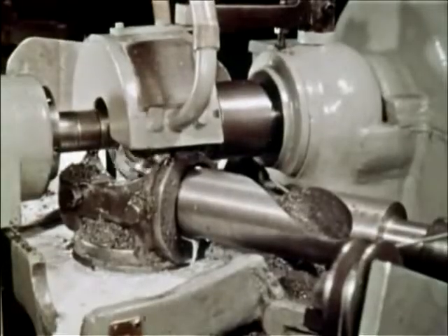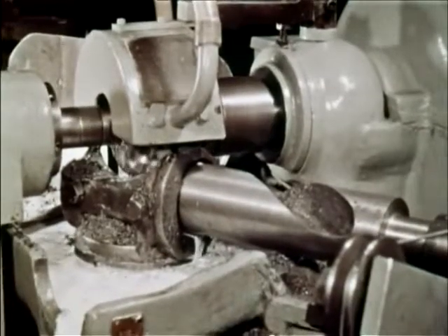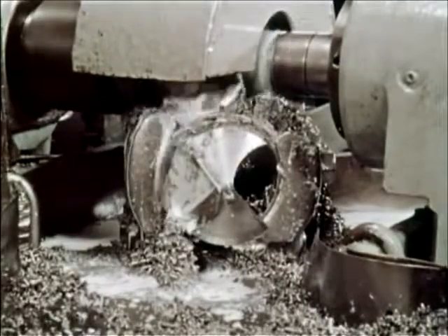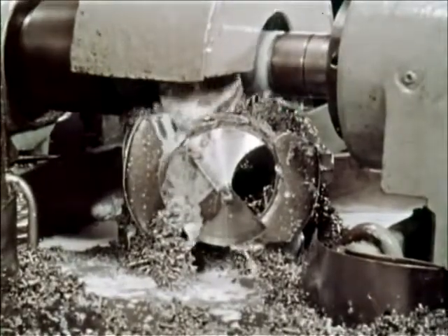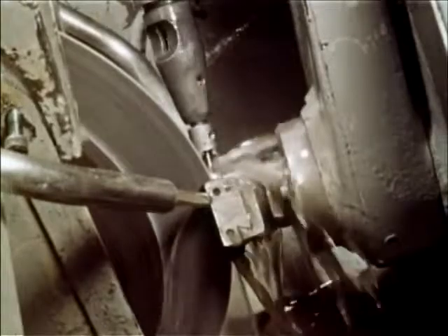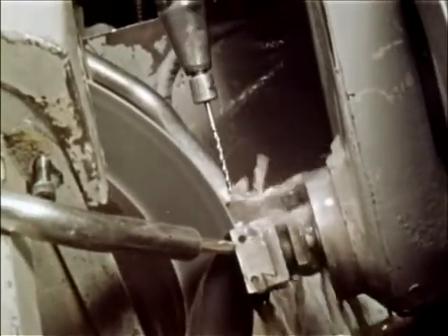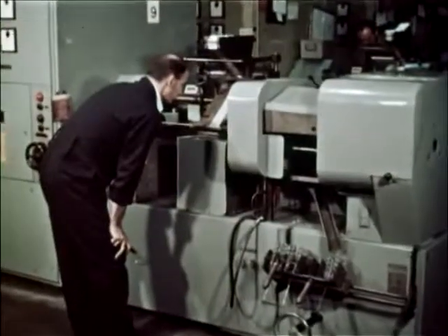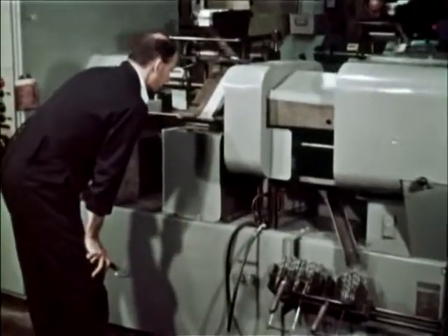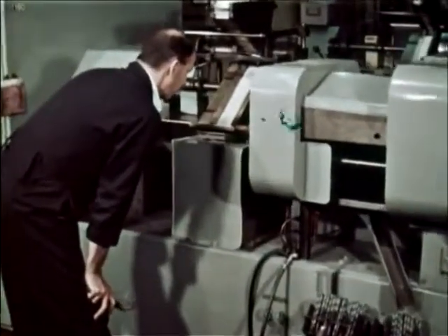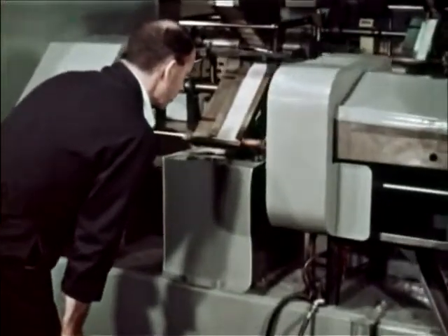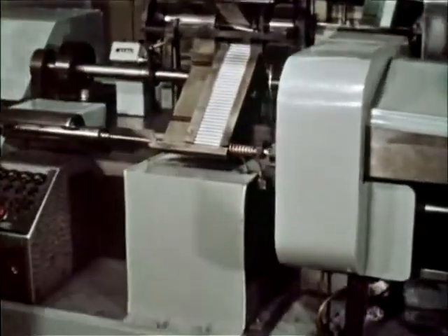The flutes of the drill are specially shaped so that when the correct point angle is produced, the cutting lip forms a straight line. The flutes of smaller drills are produced by grinding. Another method is roll forging, where the high-speed steel blanks are induction heated and passed between revolving carbide dies to form the flutes and body clearance.